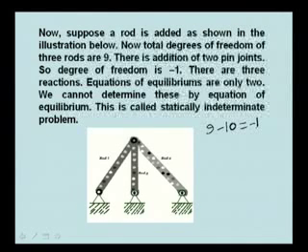There are now 3 reactions here. For the whole structure also there are only 3 reactions, and the equations of equilibrium are only 3 in 2D, so we cannot determine these by equations of equilibrium. This problem is called a statically indeterminate problem.